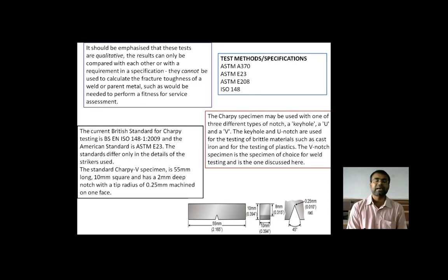So these tests can be performed according to specification, and that is to be done by the ASTM standard and by the ISO standard. From the British standard for the CHARPY test, that is BS EN ISO 148-1 2009, and the American standard is ASTM E23, applicable to identify the impact test, one of which is CHARPY.